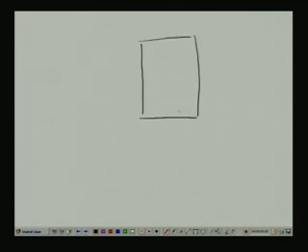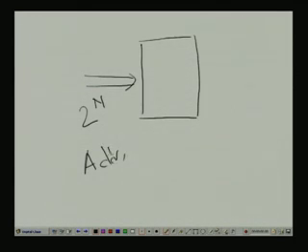So, if I consider only the OR as if it has 2 to the power n inputs, the min terms, this can be treated as addresses. So, this is an n-bit address, and from there, as if these addresses will give the values that will be taken.